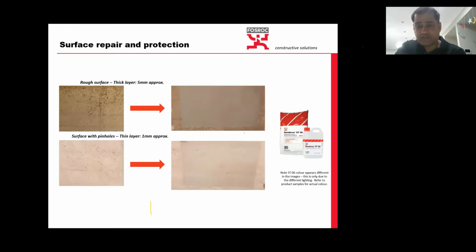So engineers sometimes face problems, like, hey, we are 20 millimeter low in cover because of some problem, the formwork slip and all that. There are products these days that could make up for the low concrete cover. However, it's very tricky. No one is going to give you in writing that they take the liability and responsibility. If it's a complete project with low cover, it's a massive problem. It's a disaster. So it has to be rectified by belt and brace method.